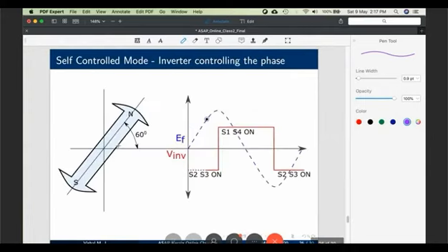Now assume that the rotor poles are at 60 degree at a given time. We cannot open the machine and see where the rotor poles are, so we are using rotor position encoders. The RPE says 60 degree.